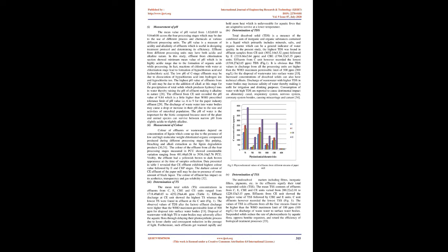The pH of effluent samples was measured at the site of collection using a microprocessor-based pH meter, Labtronics. Color of the samples was analyzed by spectrophotometric method. Turbidity of the effluent was measured by using a turbidity meter, 2100AN. The remaining effluent characteristic parameters, i.e., total solids, TS, total dissolved solids, TDS, total suspended solids, TSS, biological oxygen demand, BOD, and chemical oxygen demand, COD, were determined volumetrically/titrimetrically as per standard methods.